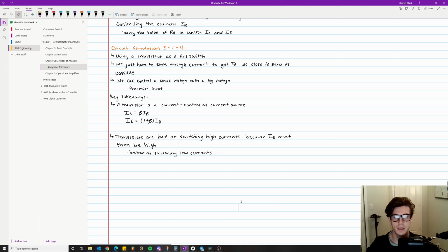And with that, that pretty much wraps up what I wanted to cover in this video. Just some key takeaways: a transistor is a current-controlled current source. The two key equations that you definitely need to remember are that IC equals beta times IB, i.e. IE equals 1 plus beta times IB. Transistors are bad at switching high currents because IB must be proportionally high to switch a high current, right? So they're better at switching lower currents, as we just saw.